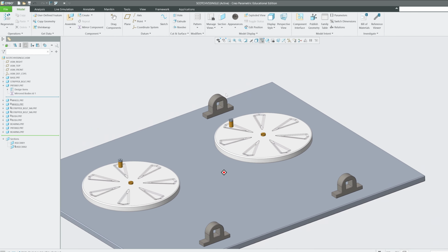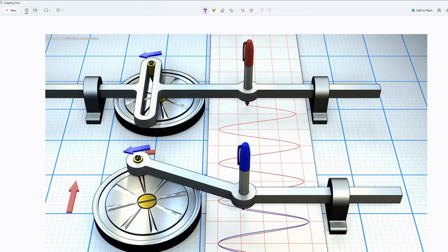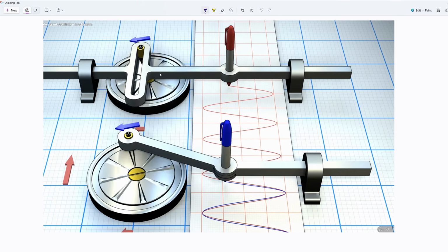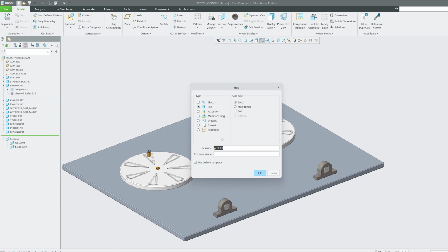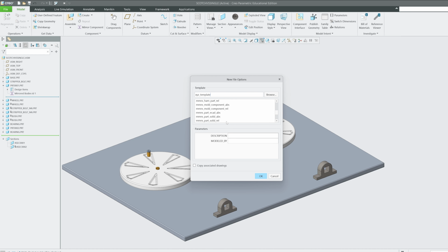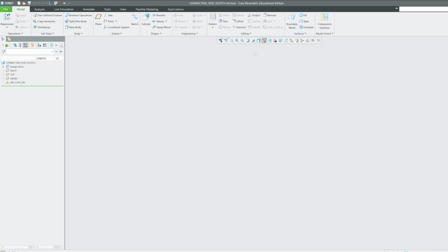Okay, now let's build this connecting rod. I'm just thinking of how I'm gonna build this. All right, so let's build this shape first, and then I'm gonna add. So I'm gonna say connecting rod in Scotch Yoke, of course, millimeter Newton second with absolute accuracy.